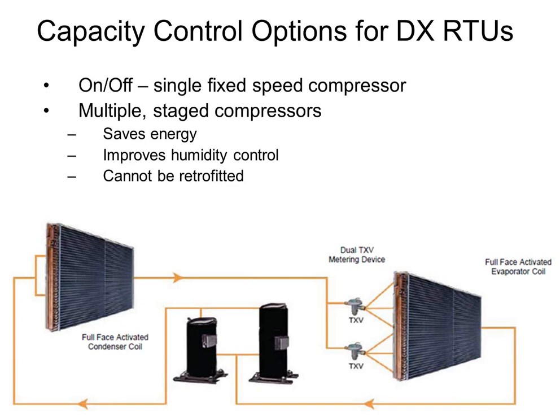If I can run one compressor instead of two, it's going to be a much better energy operating point for me. I'm going to get a much longer cycle because I won't satisfy the thermostat as quickly. I'll have milder discharge air temperature. I will improve my humidity control because my evaporator coil will be wet longer, since I'll be running longer cycles trying to satisfy them with one compressor. So if you can get 2 or 3 stages on a rooftop unit, you're usually in pretty good shape. There's very few cases where you want to use a single stage unit.